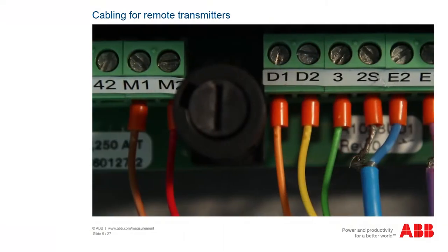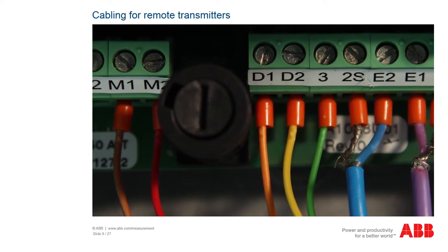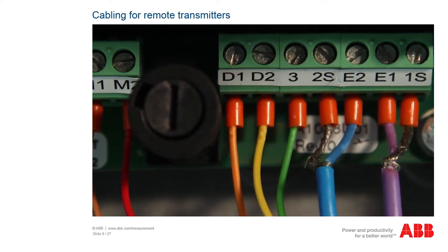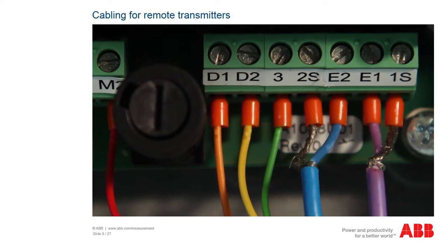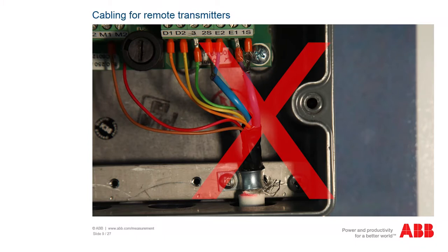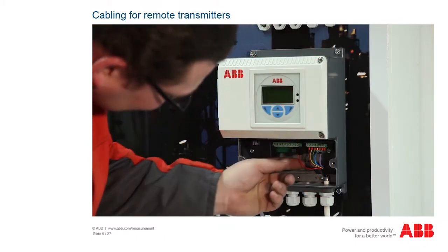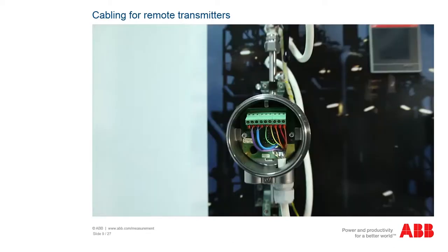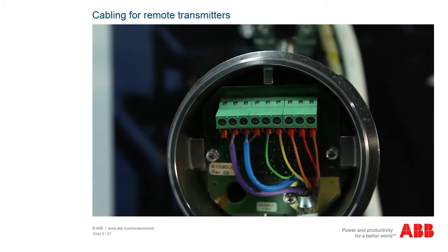With regard to the electrode leads, it is particularly important that the core of the connection leads is not damaged and that no short circuits arise as a result of the fine wires of the shielding, which may be sticking out, as shown in this example. All cables must be firmly inserted in the cable shoes as well as being firmly clamped at the terminals. The same applies to the connections in the sensor.